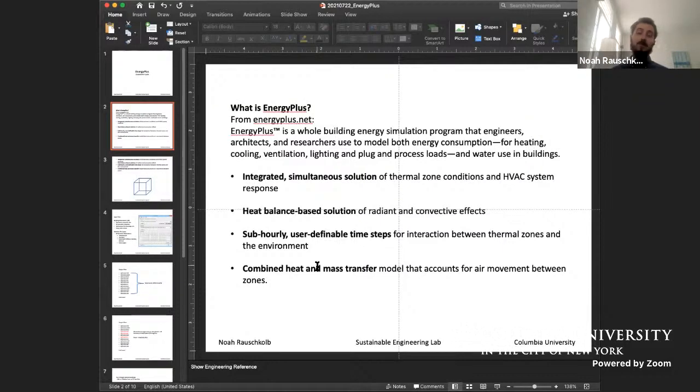And lastly, because in air conditioning you're typically moving air into and out of the space, we're also doing fluid mechanics calculations, and then the thermodynamics of having all these different things mixing. So you're pumping cold air into the room. It's probably got a higher relative humidity because it's colder and it was just cooled by a coil, lower overall moisture content.